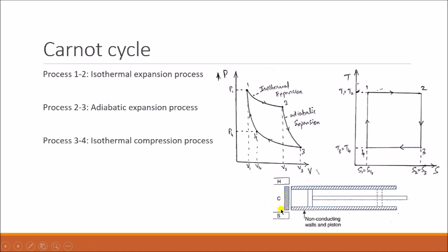So what happens is, this sink starts absorbing all the heat it had during these first two processes. When it starts absorbing, the gas loses its energy, and the piston starts coming from right to left. Okay, so that can be plotted from process 3 to 4. This 3 to 4 process we call isothermal compression.